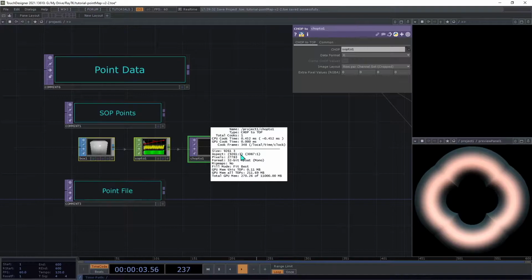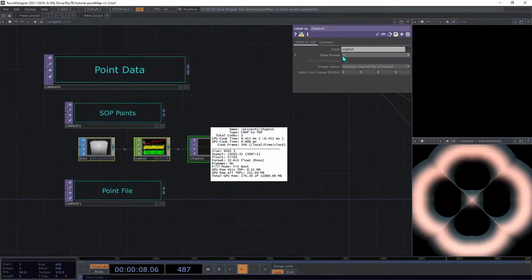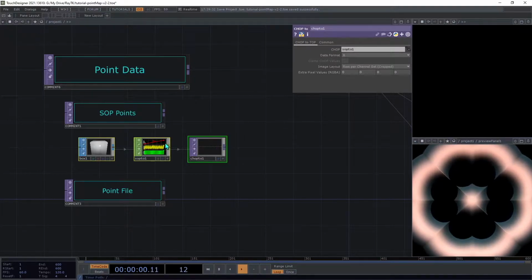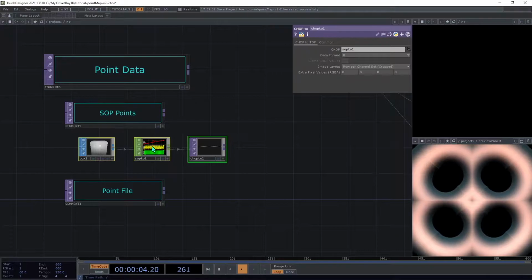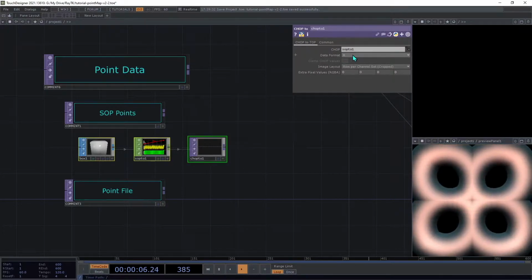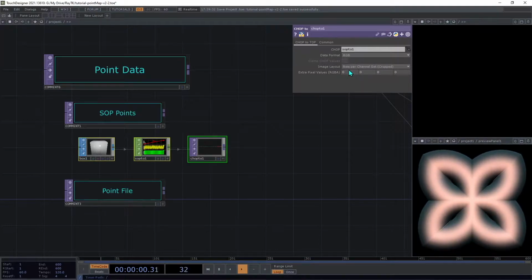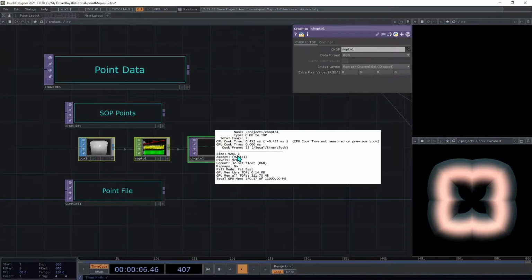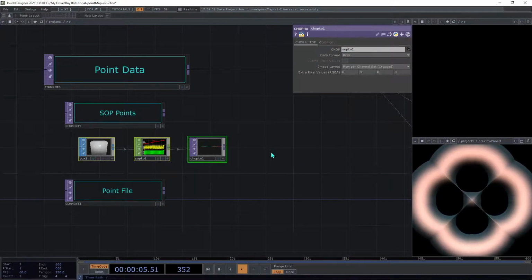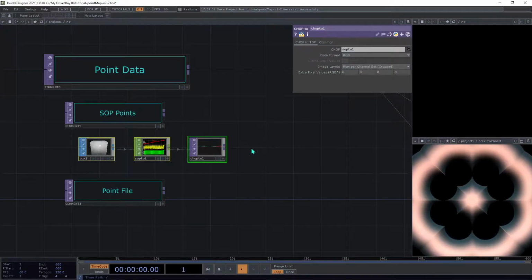It's 3 pixels high because right now the data format is red, so it's using a separate row of pixels for each of these 3 channels. What we want instead is to go with RGB. If you middle mouse on this again, you can see that it is now just a single row of pixels, using those channels as the red, green, and blue for each of those pixels.